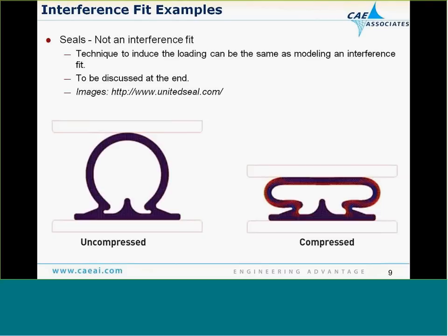And then at the end of this presentation, I'll talk about this situation, which isn't an interference fit problem, but essentially the way to model this is the same. In this case, it's a seal that's being compressed down. You could model the simulation process by squeezing that down, or you could just start off where this is going to be in the closed position, I guess. So you could start off with some interference initially in the model that way and resolve out the interference. So really the analysis technique can be the same for this type of problem as well.